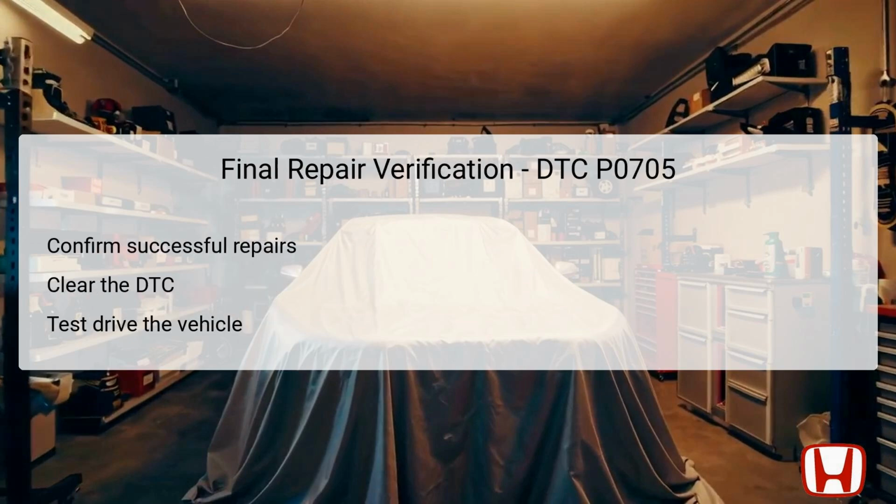After completing all necessary repairs based on troubleshooting insights, conduct a final verification. Begin by clearing the stored DTCs in the TCM using the Honda Diagnostic System HDS. Following this step, it's essential to perform a test drive to confirm that the transmission operates correctly through all gear ranges without triggering the P0705 code again. Pay attention to any abnormal shifting patterns or warning lights that may reappear. Successful verification ensures that the issue is resolved, stabilizing the vehicle's shifting performance and restoring optimal functionality.